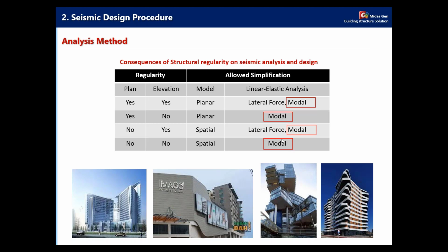That's why in your design you should use response spectrum analysis when doing seismic design analysis. You can check this building here, which is irregular in plan and in elevation. For this kind of building, you need response spectrum analysis, because the lateral force method is really limited.